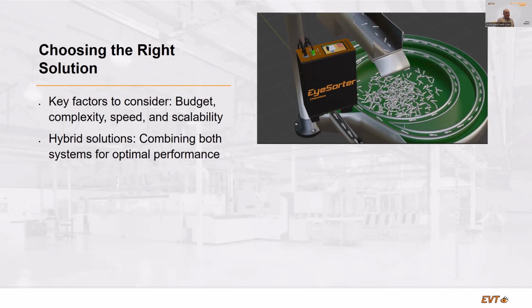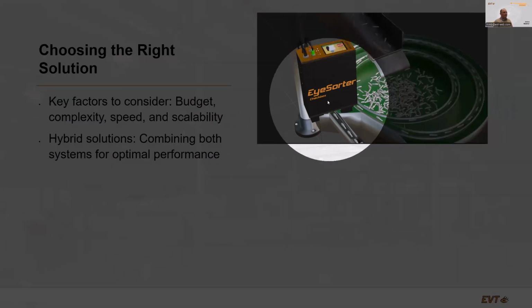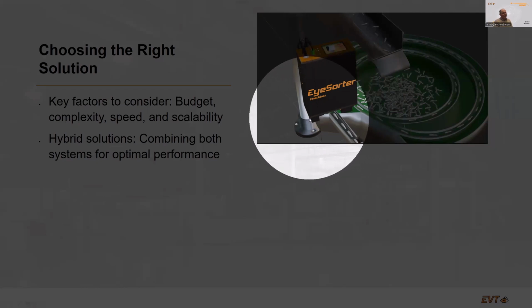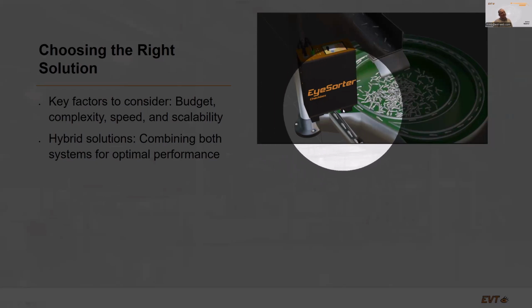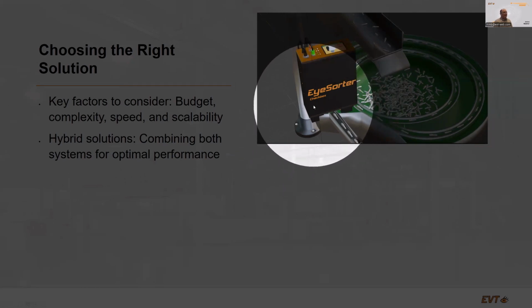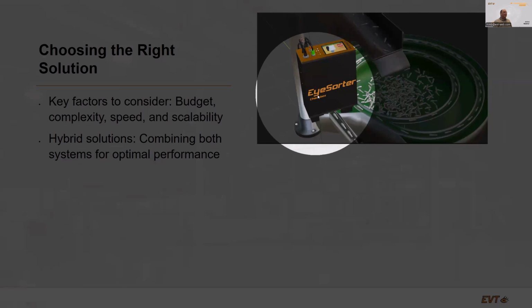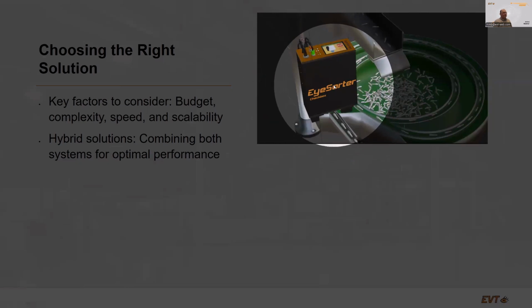You could use a smart camera and you have to attach it to the ball feeder. Anyhow, you need a light and a lens. Of course, in this case, you need a line scan camera. There are not so many smart cameras with a line sensor option. So in this case, the embedded system was the right solution.